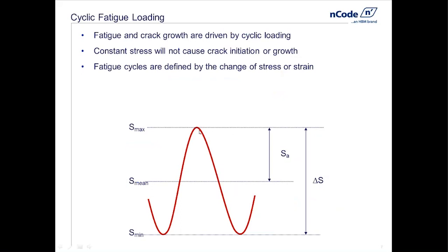What's more important than that is to think about if that stress can happen in usage, what else can happen in usage? Will our stress cycle go from maximum to say 0, or maximum to some negative value with twice the change of stress? So reversed stresses can be a very big deal. Change of stress is what's important.